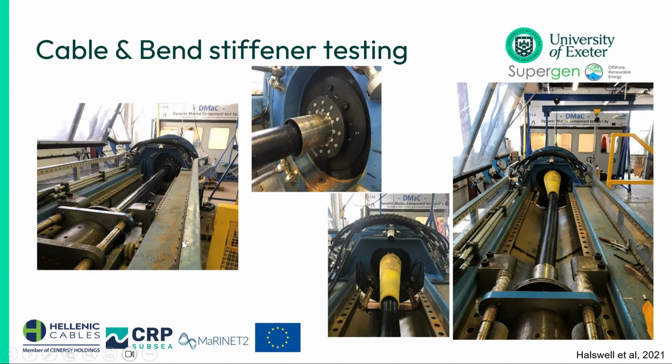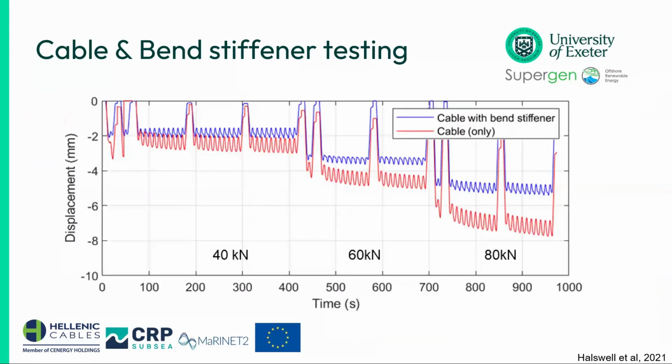Because the bending moments were quite high, we added a component here to protect our linear actuator. And then you can see the connection here, the headstock, that's without the bend stiffener, and then another cable with the bend stiffener in position. I'll show you some of the results.